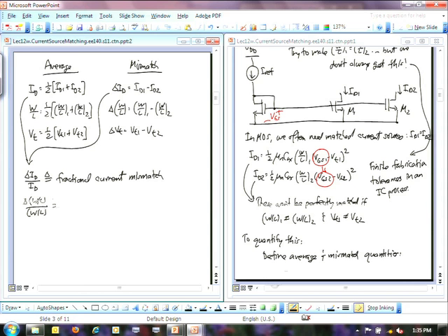And usually what I'm looking for now, well, I can see a couple things, right? So I could see that this right here, that's just ID. Okay? So I can move the ID to the other side of the equation, and I can end up with delta ID over ID is then going to be equal to moving that 2 over to this side here, delta W over L over W over L minus delta VT, divided by the overdrive voltage.